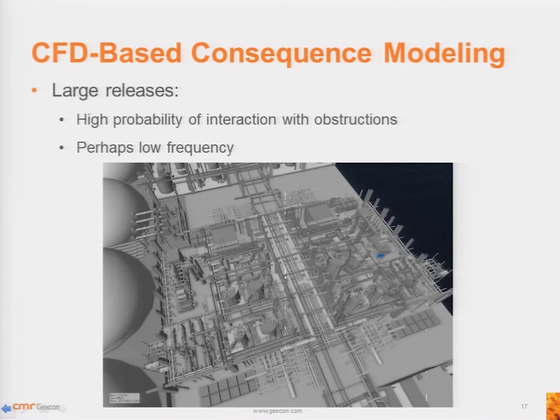Another difference of this type of study compared with onshore siting type studies is that we can't draw a circle around this. We're doing a risk assessment here, looking at specific releases. The wind direction is very specific, especially for FLNGs, because they tend to swivel around the turret, so they line up. So the wind doesn't really change in all directions. The release directions are also somewhat limited; you don't have them in 360 degrees. So again, you need to be very careful with just drawing circles and making conservative assumptions.